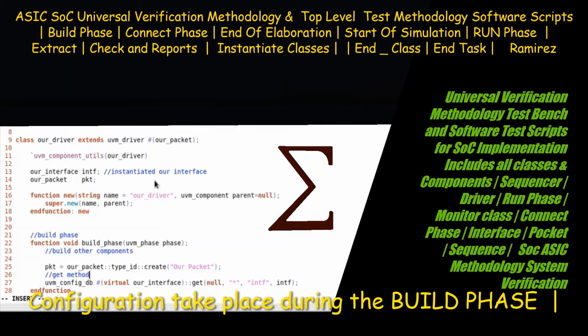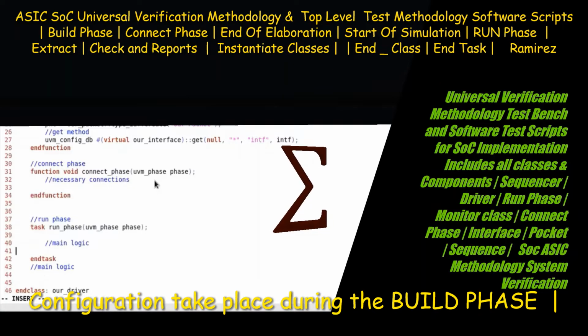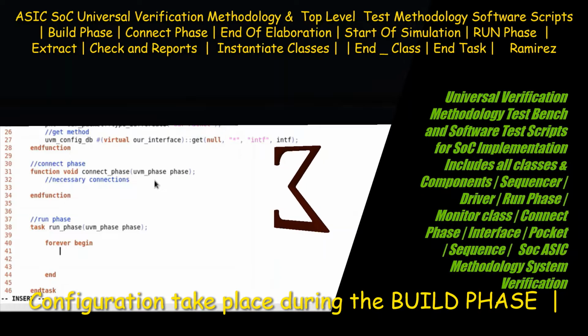The low-level components get those parameters out of the configuration database, so you can configure anything in the UVM component hierarchy, such as memory depths, file options, anything in the test bench. And you can set a virtual interface. You can get individual components out of the configuration database. The agent retrieves the information within the database.